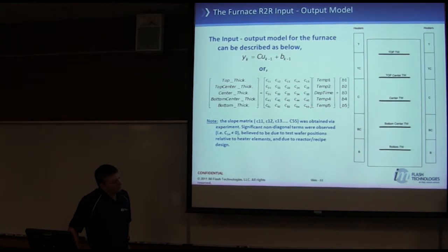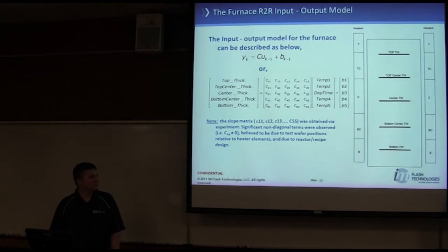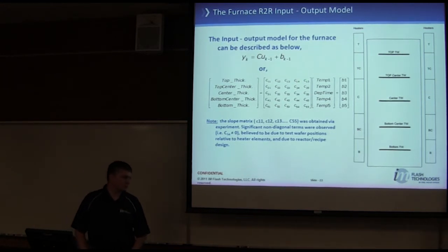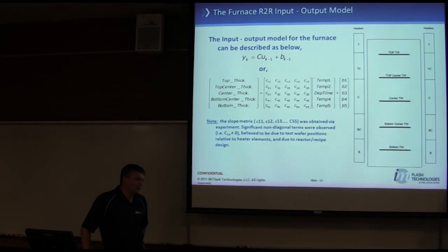basically, if you look at one of those curves, and our variation is half of our process window or more, or takes up our entire process window, then we feed that forward to another step. Now it doesn't know what to expect. I don't know if you can put a percentage on it, but we're heavily involved in some areas, like the one I just showed you with the dry etch. We can't run it manually. It has to be run with the controller. Otherwise, there's so much variation coming in.